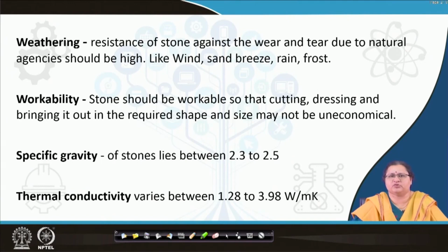Against these also you have to be very careful. Workability is the other part, which is because of the hard stones, hard rocks and the soft rocks. When you can make the Jaffrey walls with marble, you cannot make that with that of a basalt or an igneous rock. So, particularly for weathering, sandstone, very close grained sandstone is good.